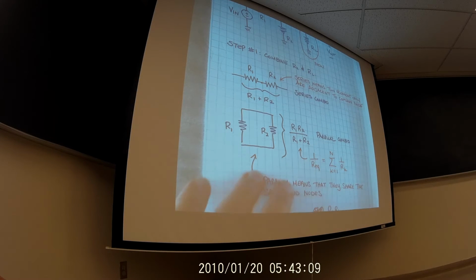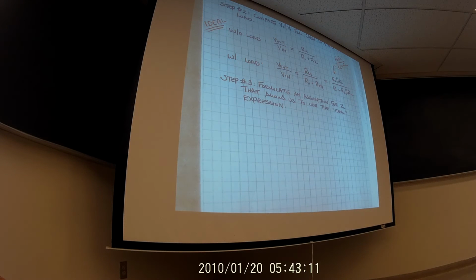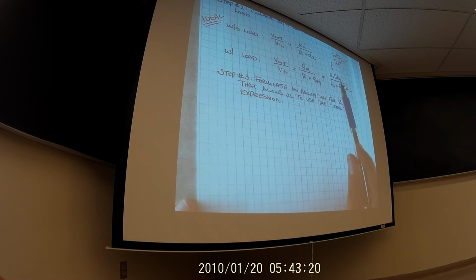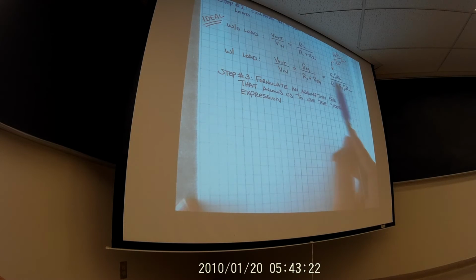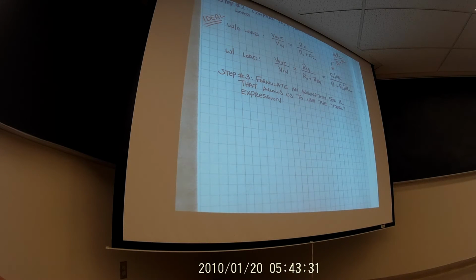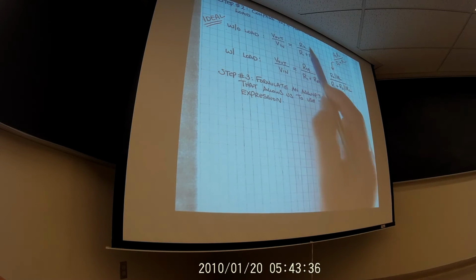So we know that to a certain point, this is going to have to be an assumption which says that RL is bigger than a certain value. Because to get this to match this over here, there's going to be a certain threshold for RL. Once RL drops below that value, then we're going to have to use this expression. But if it's above that value, with the ultimate case being an open circuit, we can probably use this over here.